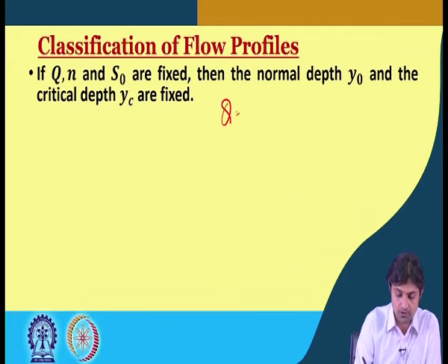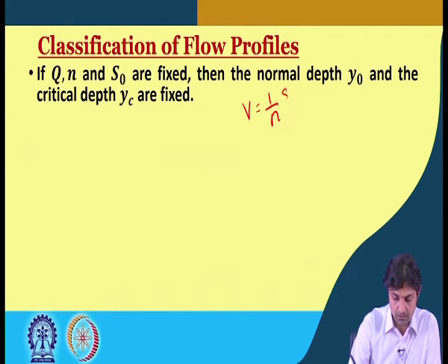Manning's equation is Q equal to 1 by n times A S to the power half R h to the power 2 by 3.